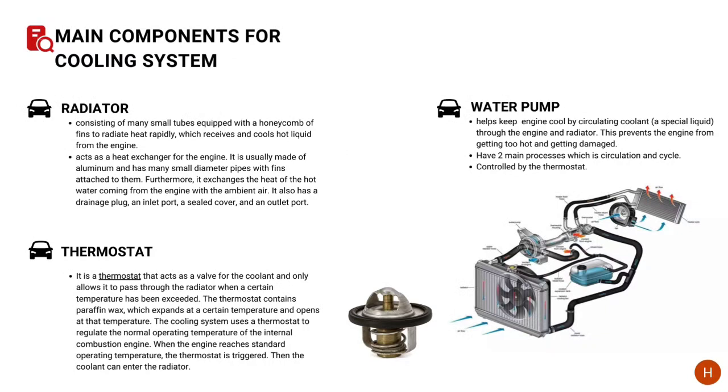The second one is the water pump, which keeps the engine cool by circulating coolant through the engine and radiator. This prevents the engine from getting too hot and overheating. The water pump also has two main processes, circulation and recirculation, and is also controlled by the thermostat.